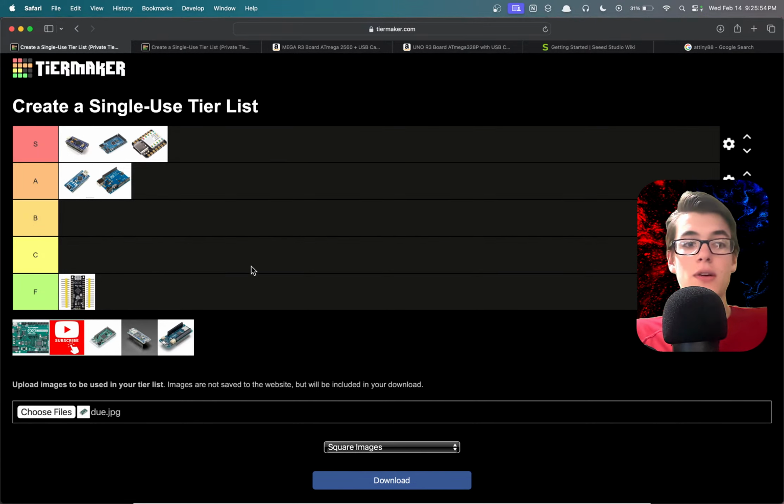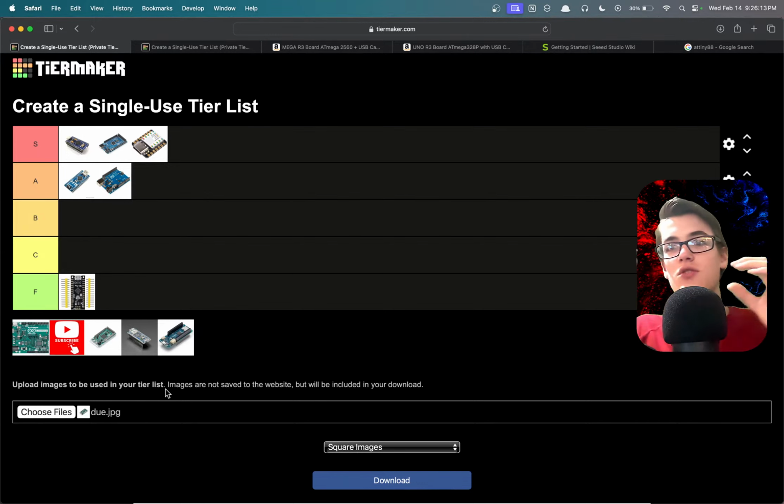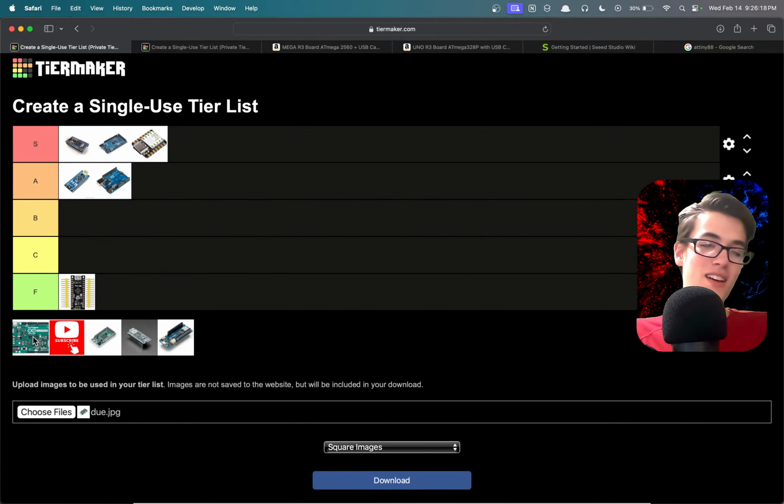Not that big of a program. Maybe like half the Arduino Nano space. Double this thing's space. Absolutely no way to cut it down. If you wanted to get a program like that running, you had to like halve the number of LEDs you were controlling. And even then, because the RAM was so small, trying to fit that array into the RAM to actually do the editing of those LEDs, a disaster. An absolute disaster. Just don't do it. Unless you know for sure that you're using a tiny program and you want to go through the hassle of that upload, don't do it. F tier board all the way.